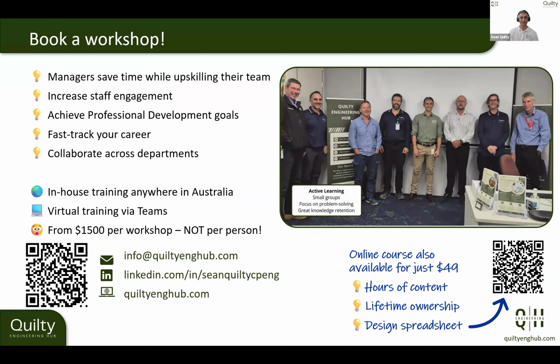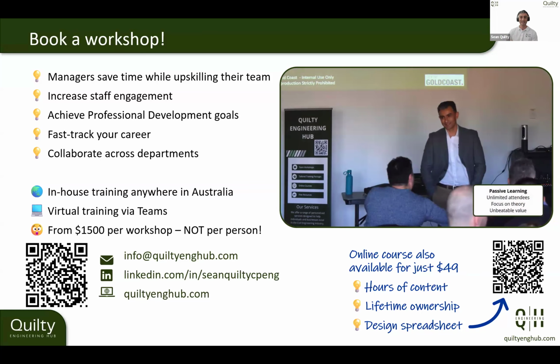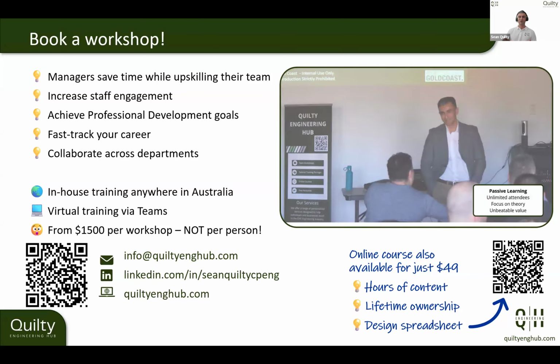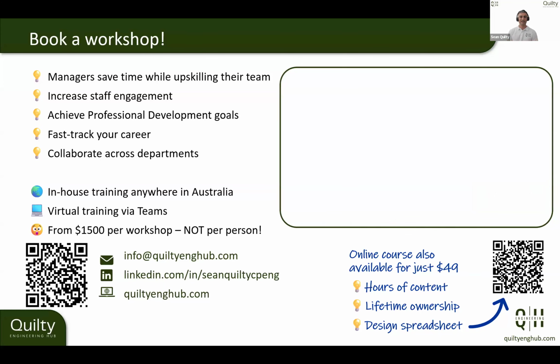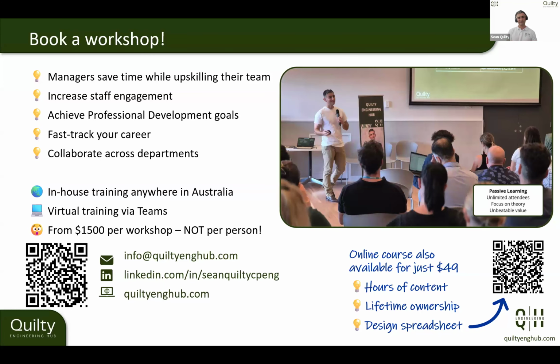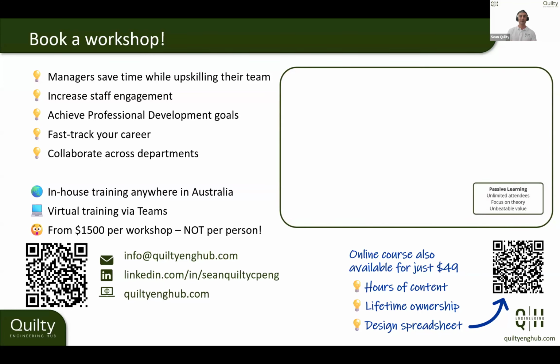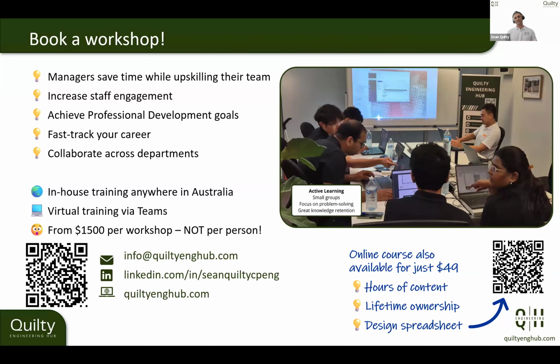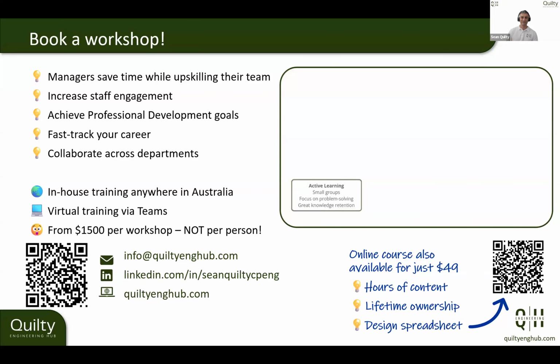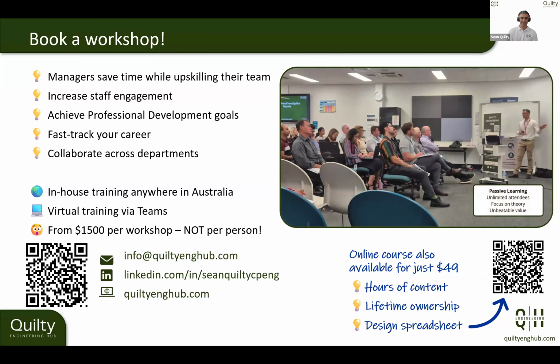I've used both in the past, and typically I'll just pick the worst case, because when we're doing these sorts of analyses, we're really simplifying a lot of stuff. And if we're simplifying it, there's a bit of risk in case it's oversimplified. So if you've got a couple of different options, I would always suggest crunching the numbers for both techniques, seeing which one's worst, and going with that to be conservative.